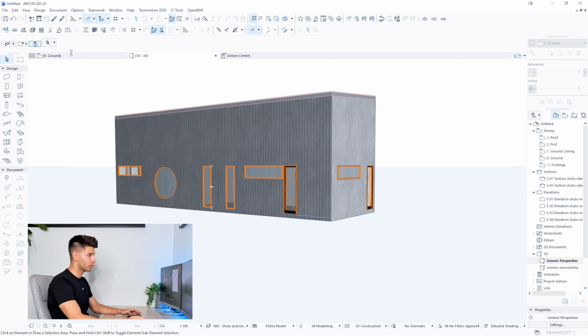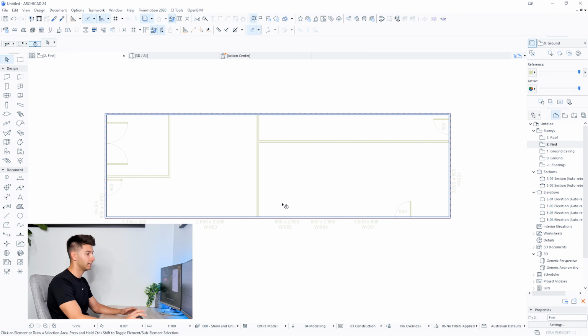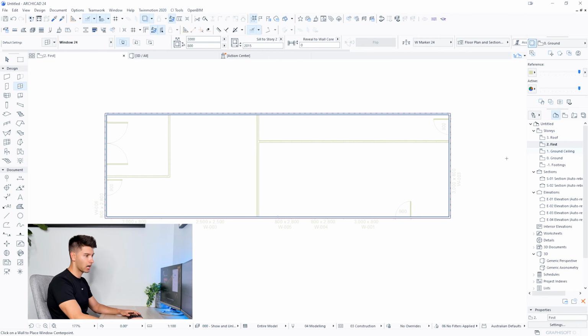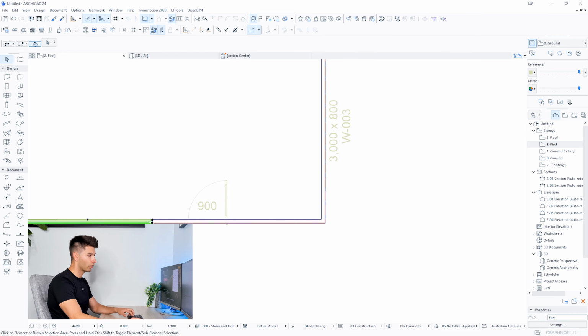Now we've got doors and windows, but only on the first floor. So we want to come back to the side panel, click on the first floor, and then start putting in some nice windows up above. Let's say we want a beautiful, long, narrow window across the whole design. Okay, so we want to move back down to our ground floor, hold Alt on one of the windows that we like, and then move back up to our first floor so it replicates those settings and we can click it. Now, let's say we want a corner window.